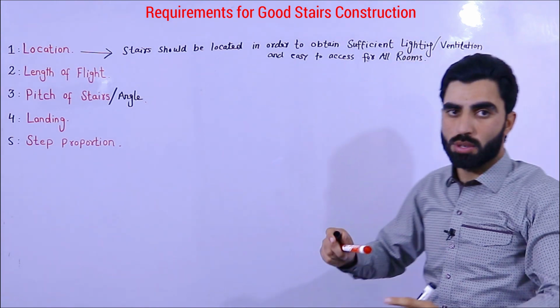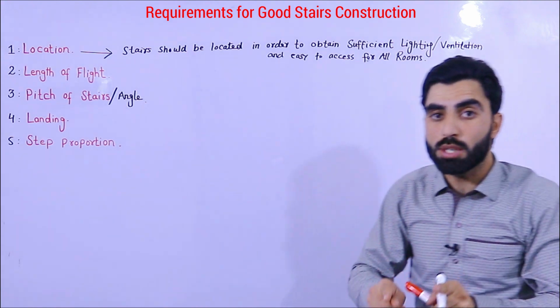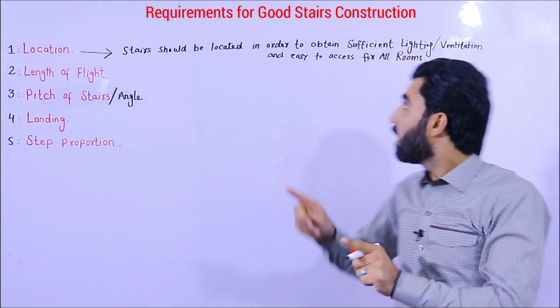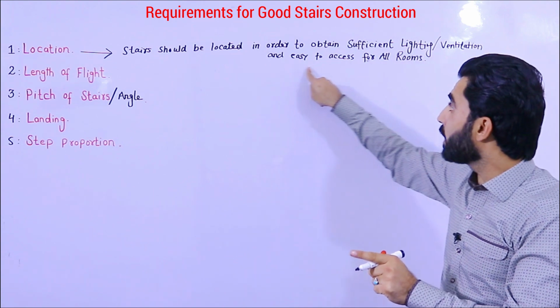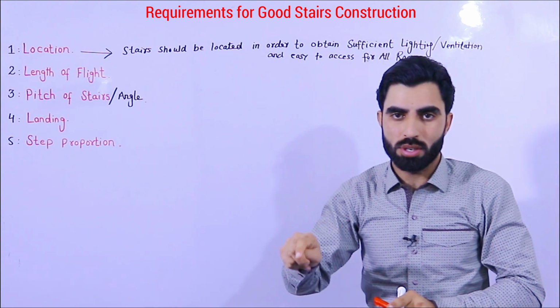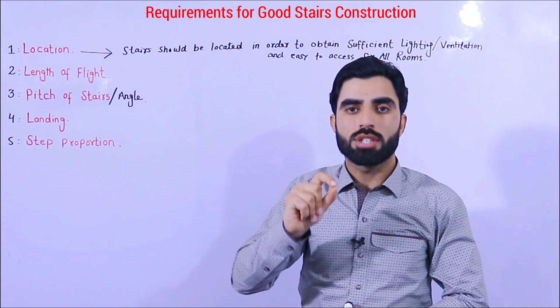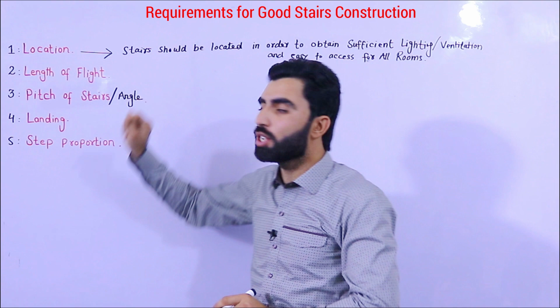This is very important. So the stair should be located to obtain sufficient lighting, ventilation, and easy access from all rooms. This is the first requirement for good staircase construction: location.